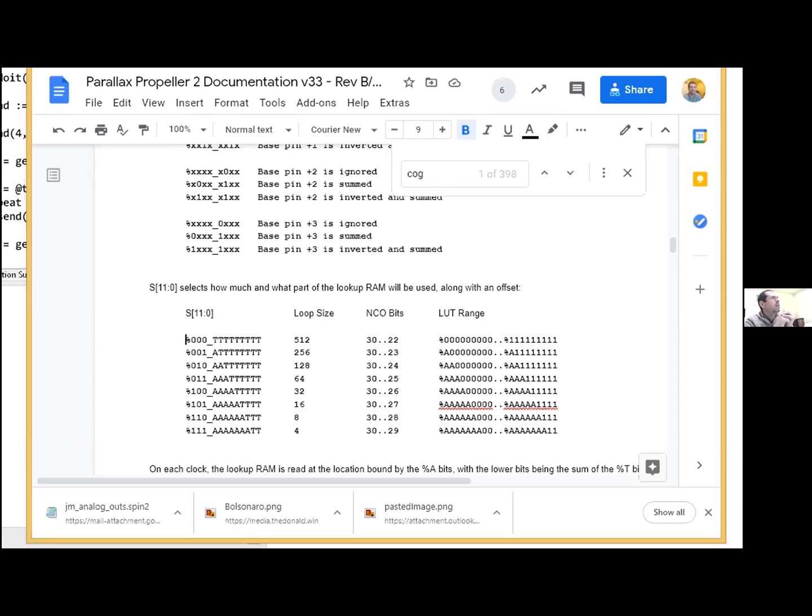And I believe you have to software control what part of the LUT is being shared. So there's no hardware gate on the portion of LUT being shared, but you can enable the sharing. It's just a 1-bit flag. There's an instruction called set LUT sharing, and it will turn that on. So you're not actually writing the buddy's LUT. You're just writing yours and reading from theirs.